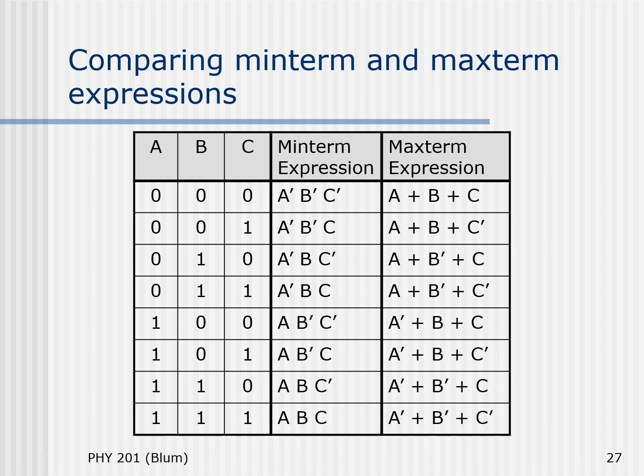Whereas the maxterm expression is trying to make a 0, and it is going to be primed when there is a 1. So let's look at row 2. We see A is 0, B is 0, and C is 1. When we're trying to make a 1, we change the A and the B, so it's A prime, B prime, C. But in the maxterm approach, where we're trying to make a 0, it's the 1 we don't like, and so it's A plus B plus C prime.